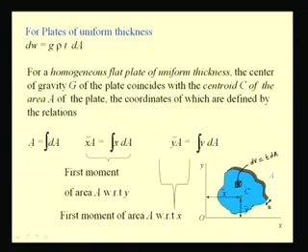So, we have the area of the plate as the integral of dA, and the first moments are x bar A equal to integral x dA, and this quantity, integral x dA, is known as the first moment of this area with respect to the y axis, because we are taking this moment with respect to this y axis.